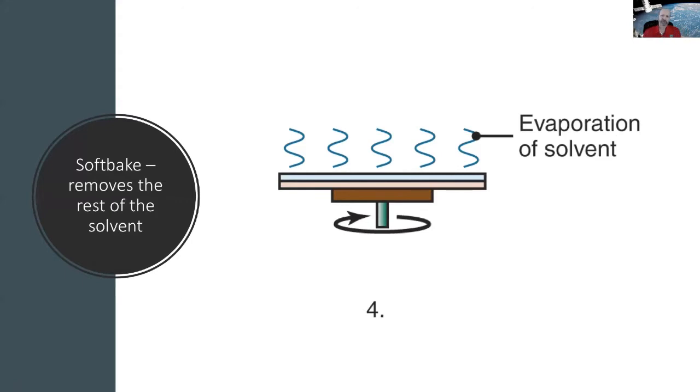If you don't have a good spin program, if you ramp up too fast or too slow, you'll get non-uniformities in the coat across the wafer, and that's important in terms of the quality of the transfer of the pattern to the photoresist. So when I was in industry, I worked closely with coat engineers. I was a photolithography engineer, and then we specialized in certain tool sets. So, my buddy Dave would do tons of tests on spin speed and exhaust flows and all of that to try to get the perfect coat.